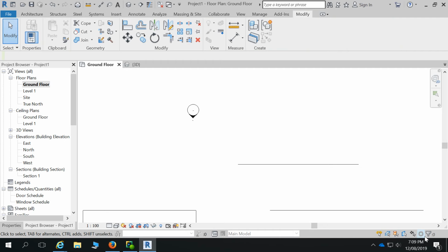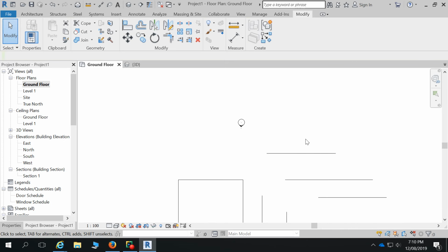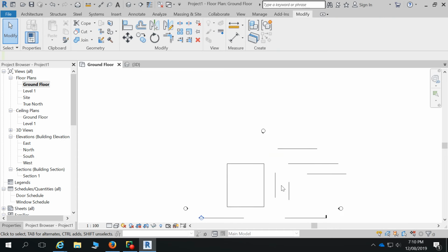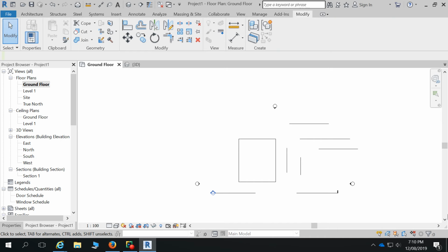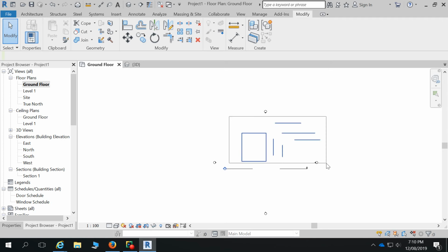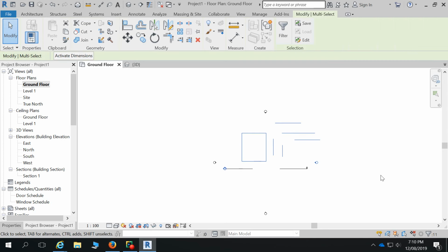You can turn it off down here in your select buttons. Down the very right hand corner of your screen, there's a series of other little buttons, little icons. And one of them has a cursor with a move symbol, and it allows you to turn off drag elements on selection, so you can't drag it accidentally when you select it. So that's a way to avoid that sort of thing happening, because you can imagine if you're in a 3D model and you went to use your select window, but you dragged along a floor of the building, it might accidentally grab it and start moving it. Happens a fair bit, because the floor is the whole plane of what you're selecting.